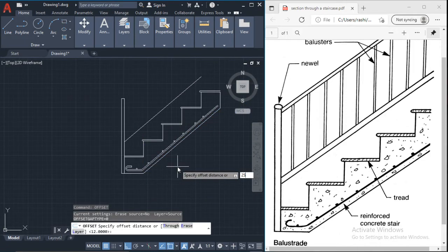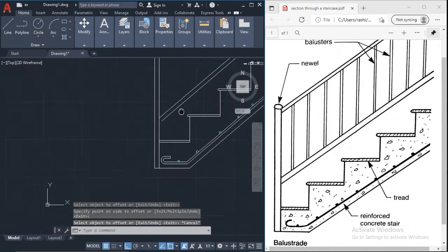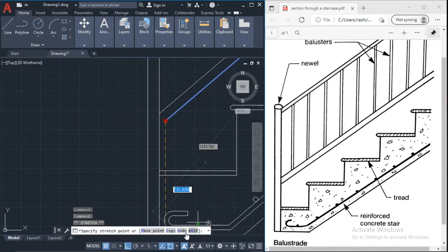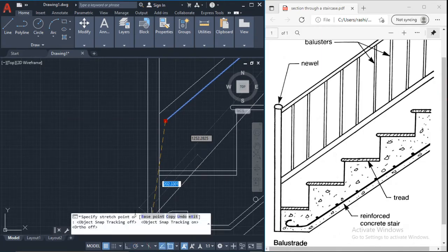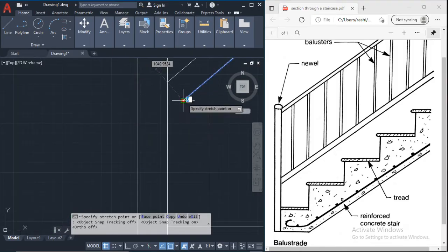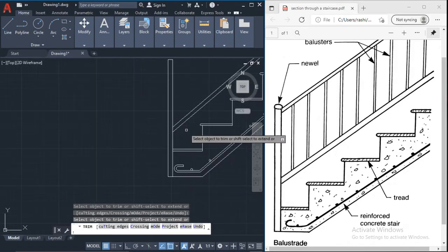I'm going to offset 25 down here, which means I need to extend this a bit. I need to turn off ortho. Sorry, not this, but ortho. And if you do that and you're not seeing it line up, just click again and you'll see the green thing, and it will come at the same angle. And I can put that piece.